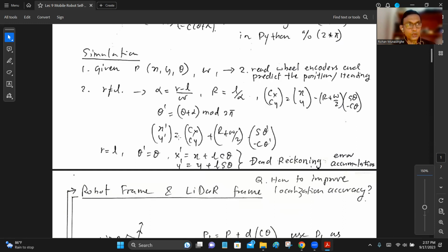However, when you get R and L equal, you are in this situation, so that theta dash is equal to theta. Your heading is not going to change. You are moving along that direction. In that case, the new position X dash and Y dash are calculated this way: X plus L cos theta, Y plus L sin theta, without any curvature. You don't need to use equations 5 and 6 because you are not going through a curvature. Straight ahead. This is a very simple algorithm. We call it dead reckoning. One of the problems in dead reckoning is that every time you have to calculate your two wheels, left and right, and you assume the wheel pulse count is proportional to the horizontal distance on the ground, on the horizontal plane of the ground, which is not a very accurate assumption because the robot goes over bumps and troughs and all that.